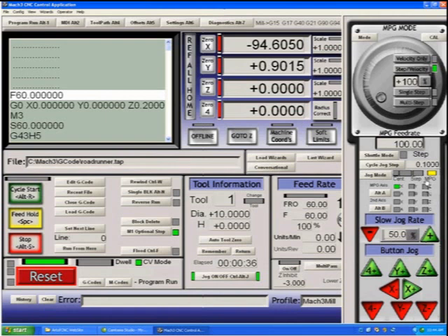We have an MPG mode, and in the MPG mode, when you rotate your MPG wheel, you will jog in one of 4 various types of jog. By selecting velocity, the faster you turn the jog wheel, the faster your axis will jog. Step velocity at the moment is the same as velocity only. It is a redundant mode and no longer required, but I'm going to leave it there for the moment. We'll fill it with a better mode soon.